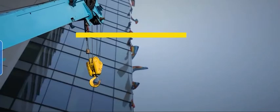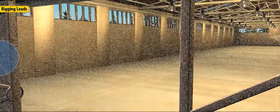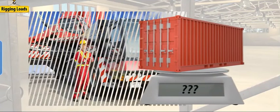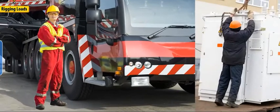Lesson 4. Identify safe practices for rigging, loading, and crane operation. It's important to rig loads properly. The first step is identifying how heavy the load is. Crane operators are responsible for knowing if the crane can handle the load before trying to pick it up, and operators and riggers can only decide the proper kind of rigging for the job if they know the specific weight.